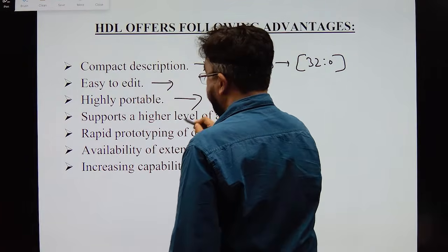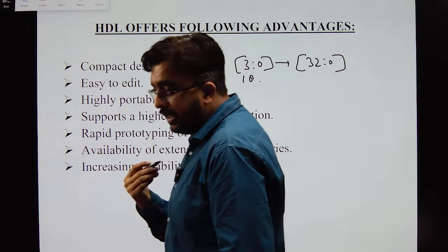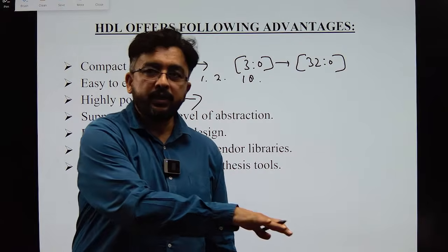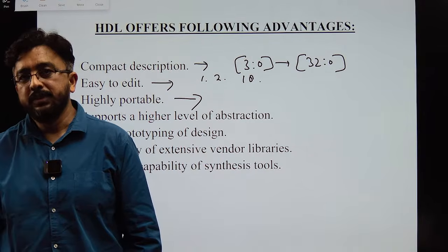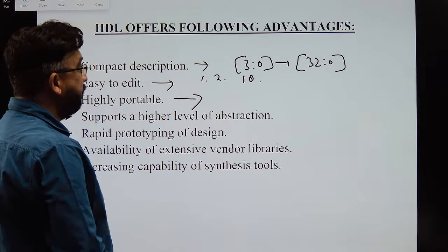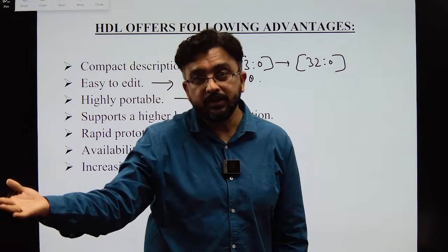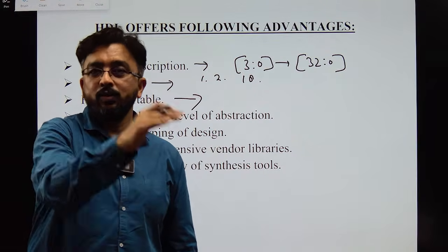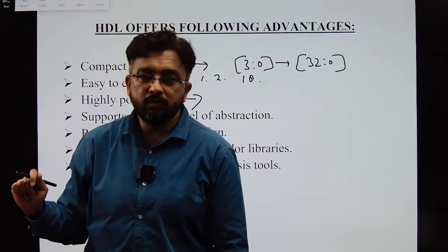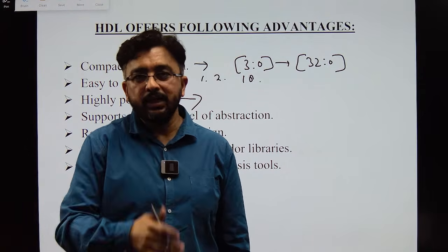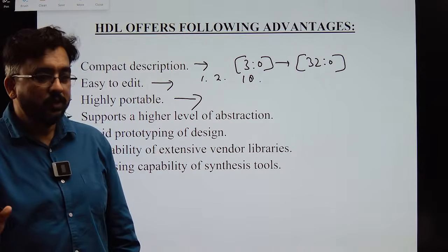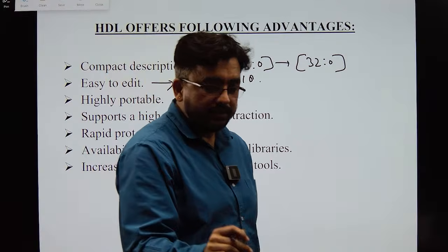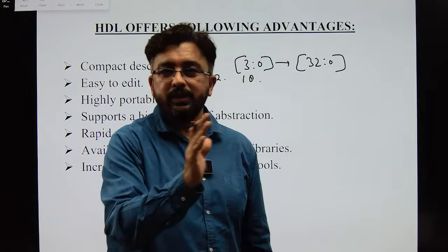Highly portable. If I have written anything in Verilog in Xilinx, I can convert it into the Altera tool. That is called portability. But the schematic cannot be converted. The schematic cannot be converted from Xilinx to Altera, or from Altera to Lattice, or from Lattice to QuickLogic, or from QuickLogic again to Xilinx. It is not easy to convert the schematic from one vendor to another vendor.